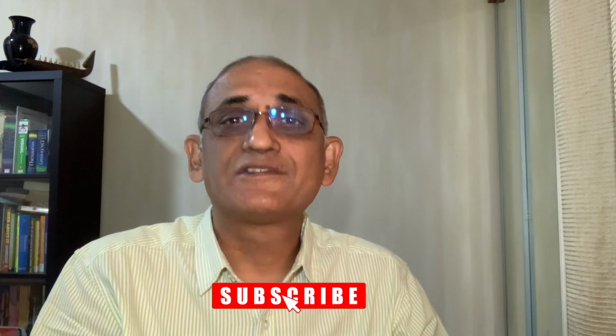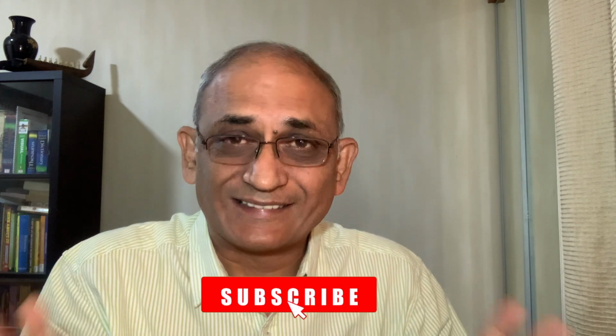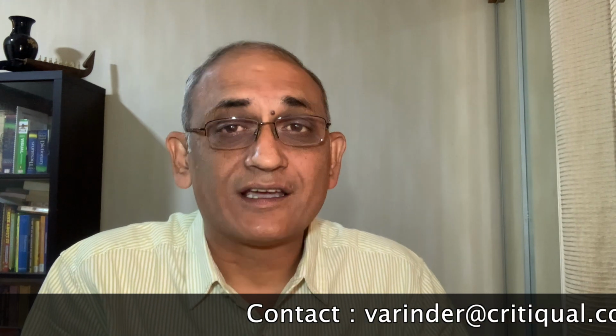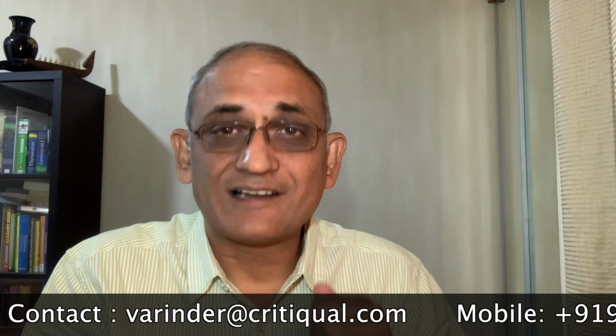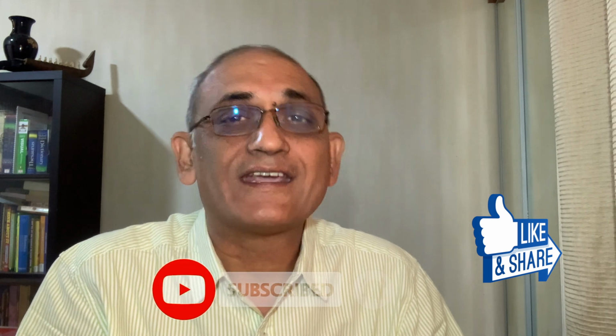Just remember one thing: every time a breaker trips, the root cause of the tripping has to be established before you put the breakers back into service. Nuisance tripping hardly ever exists. Most of the times there is a reason behind a breaker tripping. So if you have found a breaker which is, according to you, tripping without reason, or if your upstream breaker is tripping without the downstream breaker clearing the fault, it is time to call an expert and have the breaker coordination checked out. And if you want to be proactive, you can always have a breaker coordination study carried out for your facilities to eliminate any problem areas.